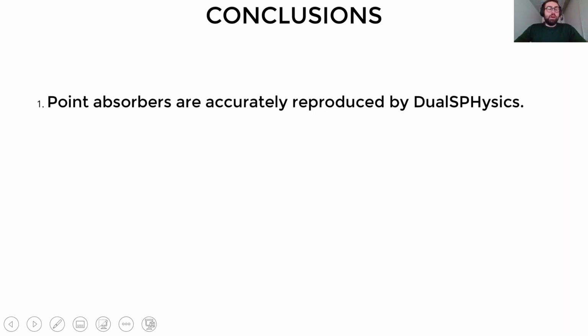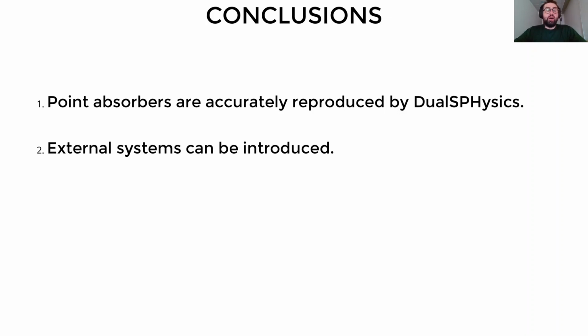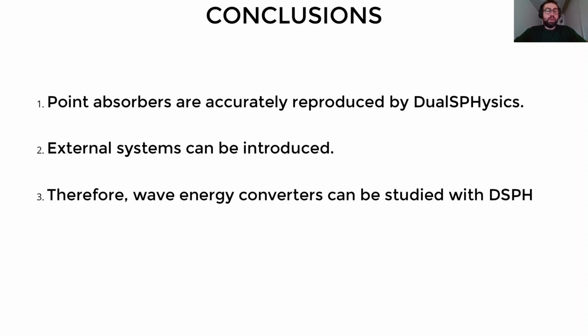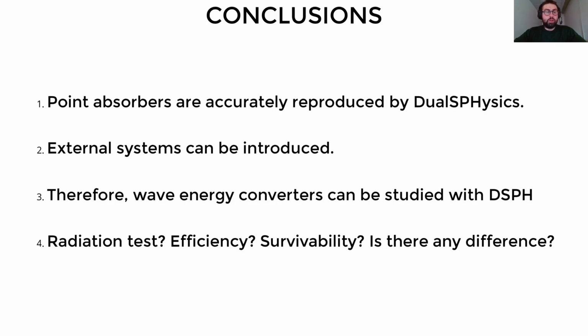Concluding, DualSPHysics can simulate point absorbers, and this was demonstrated during my presentation. All the external systems that should be introduced to control the movement of a buoy to turn it into a wave energy converter can be easily handled thanks to the coupling with the Project Chrono library. So we can conclude that point absorber wave energy converters can be studied with the DualSPHysics framework.